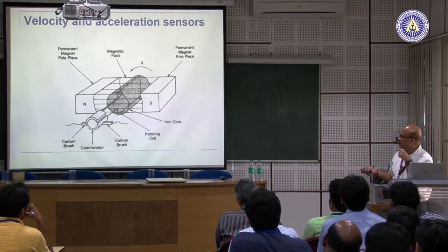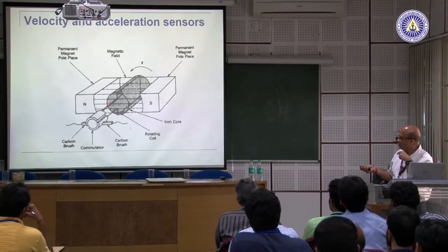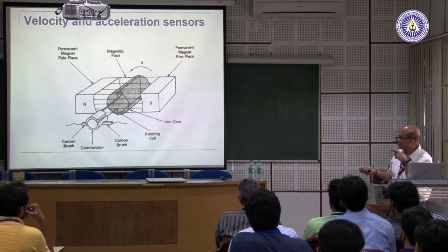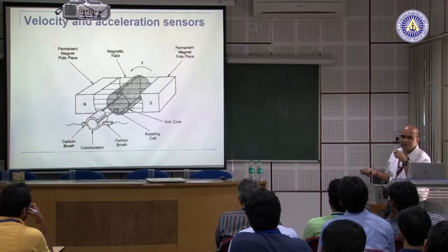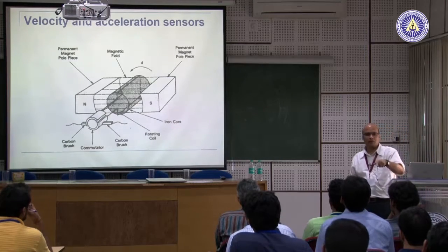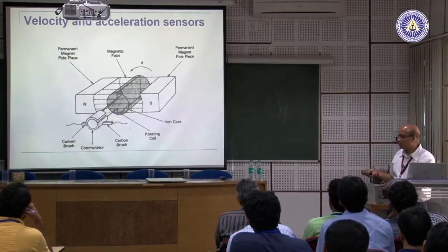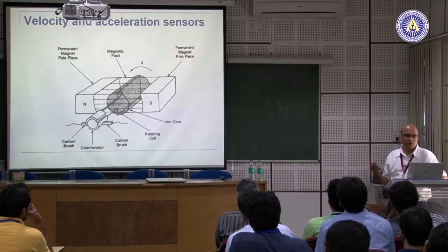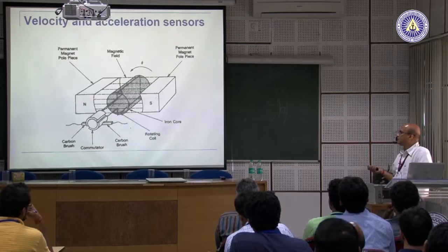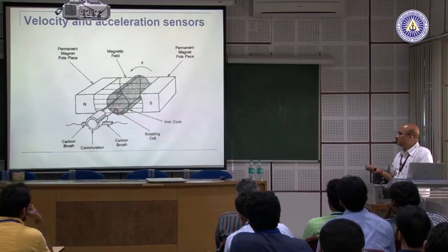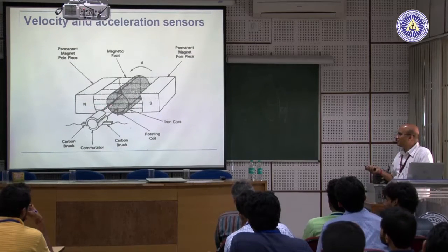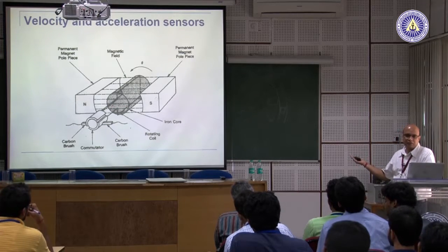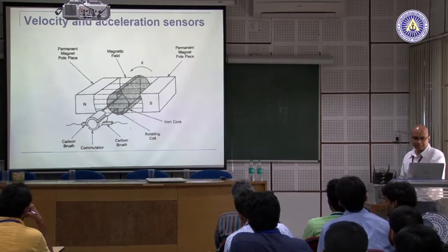So, if I have some kind of calibration between the voltage that is generated in there and the speed at which I am rotating, then I can have a straight line and draw a graph. Then for any voltage, I know the corresponding speed. Now, that is essentially what we call a tachometer. A tachometer is essentially a DC motor, and it converts the rotating speed into an electrical voltage, and by measuring the voltage you can say what the speed is.